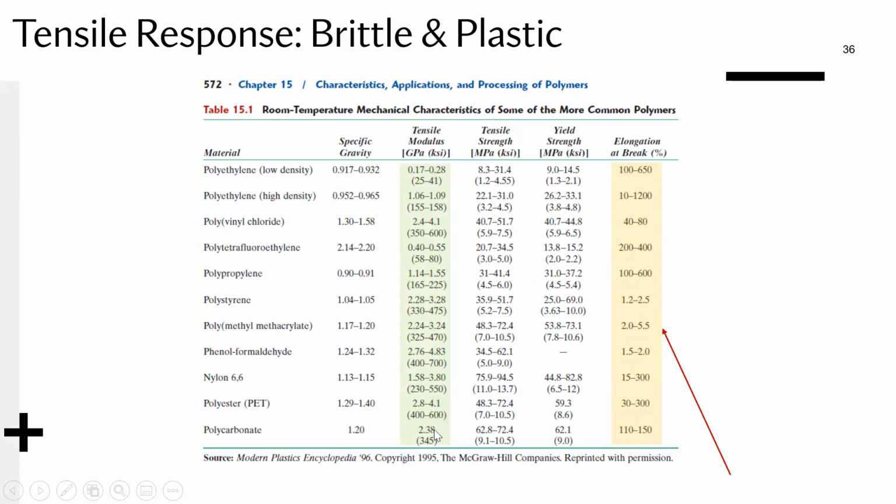Okay, so you can also see quite a range here. If you remember, in terms of the ones that had brittle behavior, the slope was a lot higher. So you can actually see that increased slope means increased elastic modulus. In this case, if you have an elastic modulus a bit higher, elastic moduli as large as 2.7 gigapascal, that is a rather stiff material. So I would expect that it has a brittle behavior, and it does.